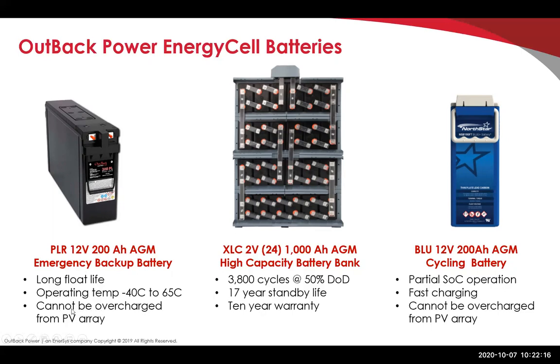The other thing that's pretty cool about this battery is it cannot be overcharged from the PV array. And you'll notice the same thing with the blue battery. Why this is important is, in some cases, we've seen people who want to go big on their PV array because they want to net meter and self-consume, and they want to go big on solar and small on batteries. The risk of that is if you discharge your batteries overnight, say, to avoid some time of use charges, and then you start the morning with a battery that's half empty or less, and you don't control the charging from the array, you could easily overcharge the battery.